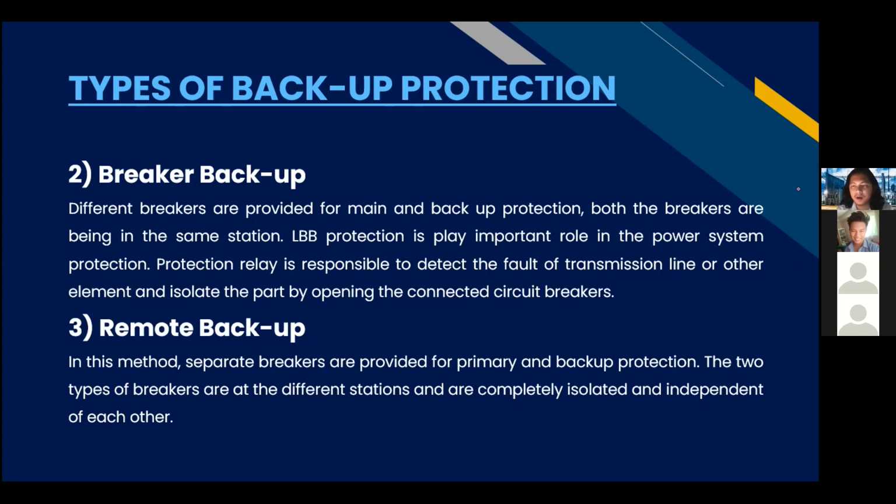Both primary and backup protection can be found in the same station. It is used as backup protection of the circuit to isolate the fault in case the circuit breaker fails to trip. If any trip relay operates, it will send the trip command to the circuit breaker and also send a command as breaker backup initiation to the breaker backup relay to activate.